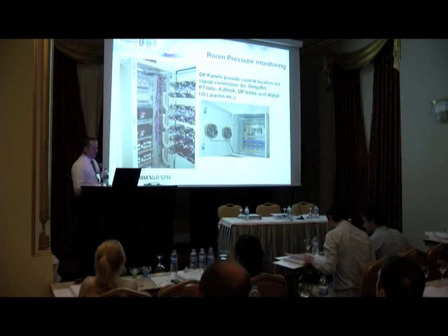But there is a utility here that perhaps if you have shut the clean room down, you've got someone who's logged on who's a manager level of the system, we haven't really touched on the different operator levels, but if you're a manager level of the system, you might want to, rather than acknowledge all the alarms individually, say we've taken the clean room down, so we're doing maintenance. And you might just put a comment in to acknowledge all the alarms with a comment of maintenance by whoever, and then tag the user who's made that acknowledgement.